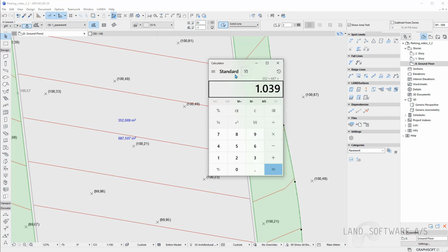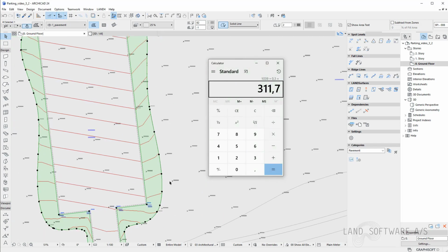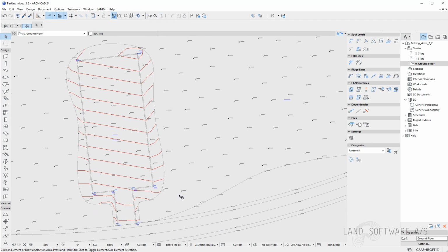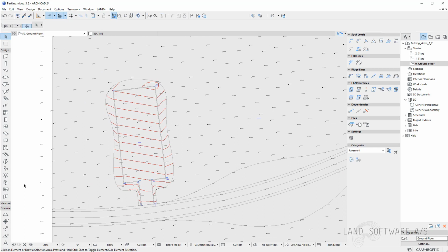So this is my total area, and I used about 0.3, so 30 centimeters in thickness. So I will have roughly 310, 311 cubic meters to bring to the construction site as surface materials. Therefore, I also need to take this into account because they will be basically calculated in the total volumes we need to add to the site.